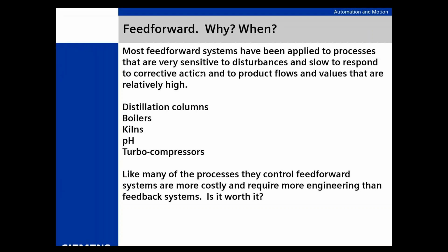That's something that you do when you have to. If you don't have to do it, you don't do it. But certain things, again, distillation columns, some boilers and things, I want to control my boiler before it lifts all the safety valves. So I'm going to probably use feed forward if I can. If it's a real small package boiler, it's no big deal, then I wouldn't mess with it. I don't really need it.